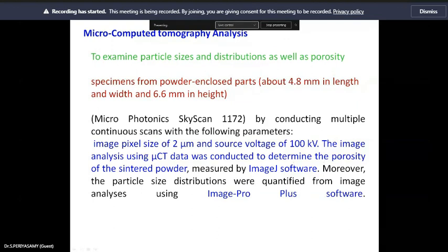One layer will shrink more or one layer will expand more. In those cases you can have an induced strain, a residual strain will form, and then the stress will automatically be built in. Here the tensile stress will be deposited on the new layer and creates a compressive stress at the bottom layer.